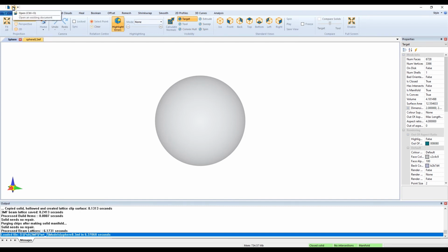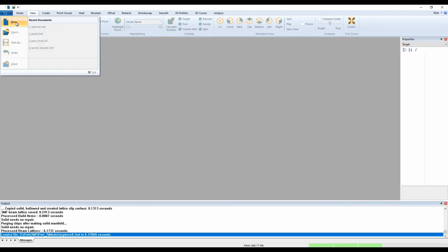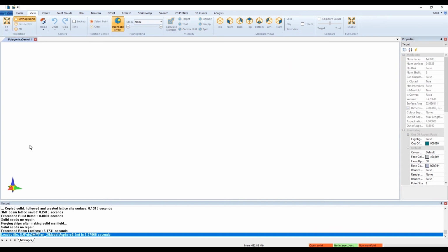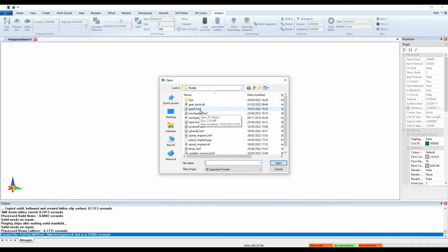But you don't have to make the mesh explicit on import. For example, we can load it in and slice it, as explained in our previous video, slicing and 2D profile operations, lattice creation. So let's close these spheres down. Don't want to save that. And now we'll create a new window, and then we'll load the file in using load and slice, which will create 100 slices through the file from the instance world entities without needing to do a full Boolean first. So go load and slice, sphere, let's open it back up.